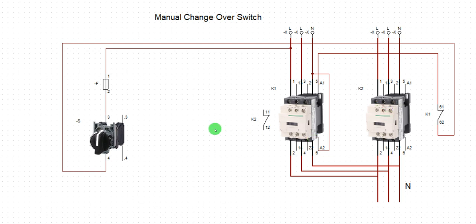But for the sake of the challenge we have, we're going to use this one just without neutral. We're going to use only 2-turn. The issue is this: once I put on my simulation, one power is activated already. At every given time, one of the contactors must be closed. So when power comes available, it will enter immediately. So I cannot put in neutral to carry out maintenance. So remember, I repeat again, ensure that you use 3-turn for this connection. Okay, let's proceed.